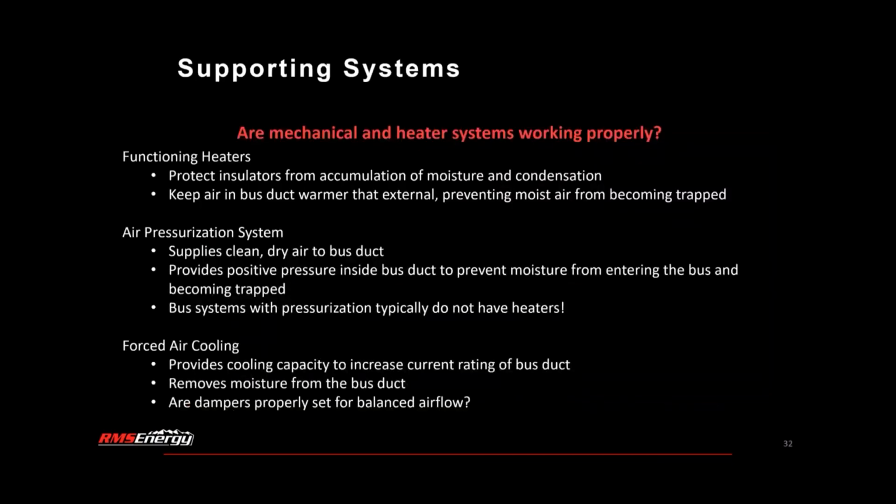So we mentioned some supporting systems that can be found in bus duct. Again, these aren't going to be located on every bus duct design, but they are important to maintain if your bus duct has these supporting systems. So a couple common ones are functioning heaters. These are commonly found on outdoor bus duct. Heaters are located at insulators to protect them from accumulation of moisture and condensation.